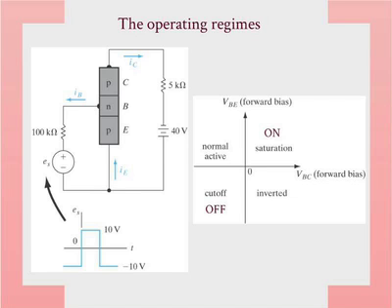Okay? Yeah? I remember maybe the first year we were talking about this, you said that the base is smaller, so holes can get across. But we always draw these, they've always looked the same to me. Yes, the schematic is not quite right. But remember, the base has to be physically a lot smaller than the emitter and the collector. We'll see that soon. Because the holes must diffuse across. They shouldn't recombine too much. If you lose them by recombination, then your amplification factor goes down. Okay. Physically, it has to be tight, small.